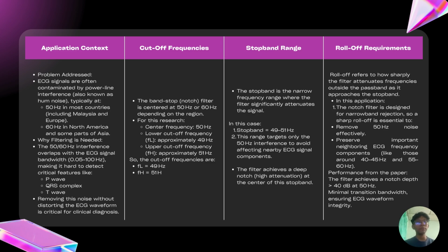The performance from the paper: the filter achieved a notch depth of more than 40 dB at 50 Hz, with minimal transition bandwidth, ensuring ECG waveform integrity.